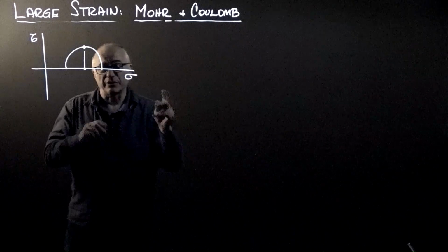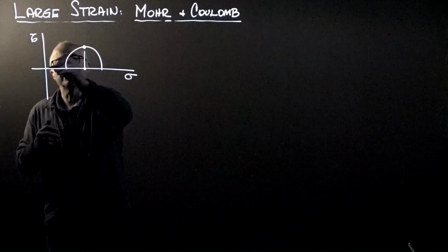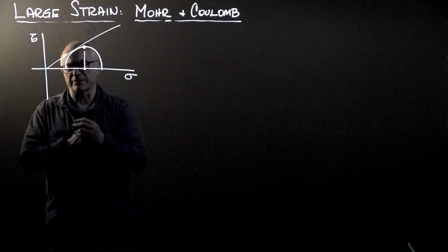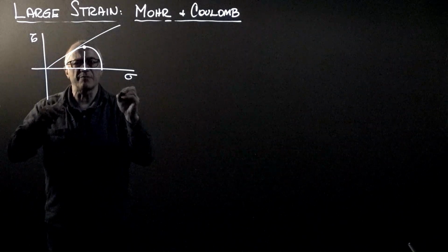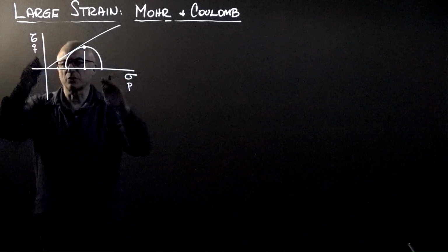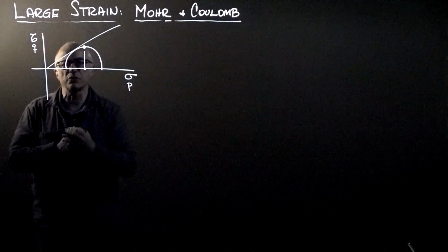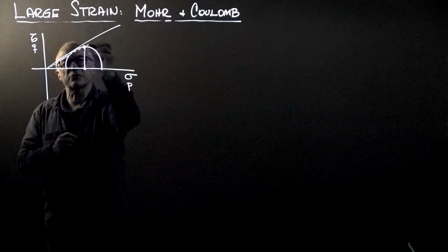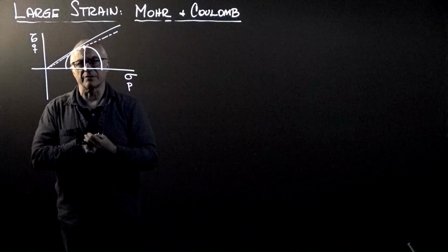However, if we are only going to follow apices, we don't know when the circle reaches the failure envelope, because the apex is not touching the failure envelope. So if we are going to work only with the apices, that means we're going to be in the QP space, which is totally coexisting with sigma tau. If we use this definition of QP, then we need to define this other line that actually goes through the apex, so we'll know when the circle has reached the failure envelope.